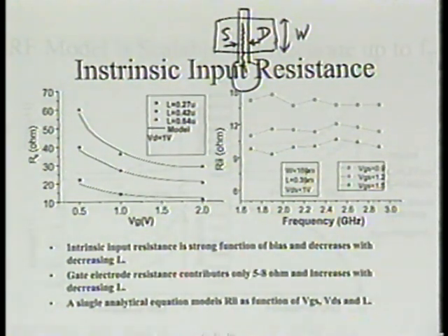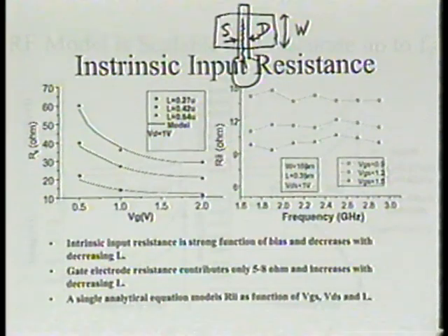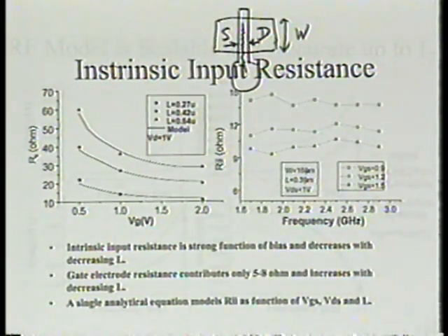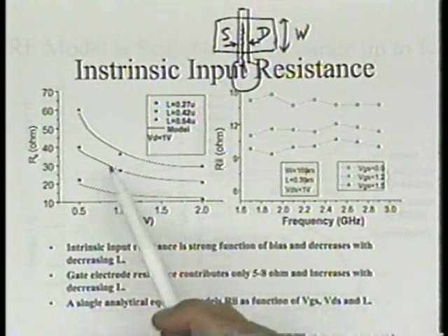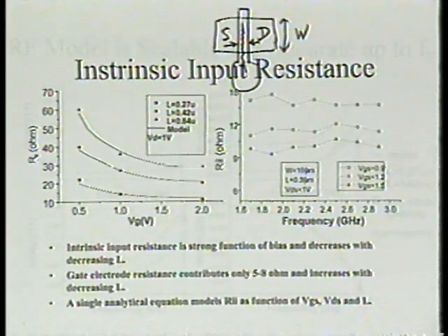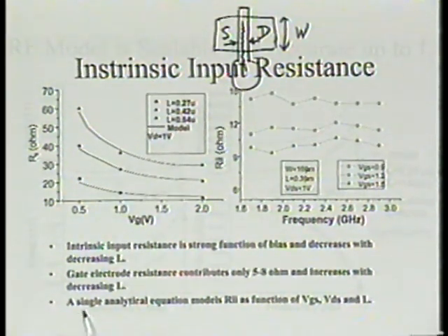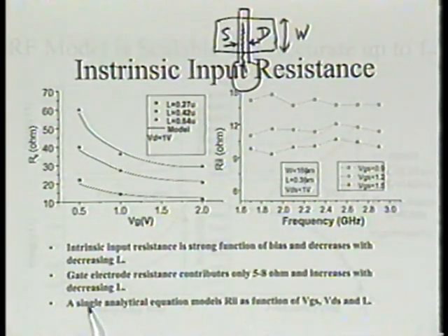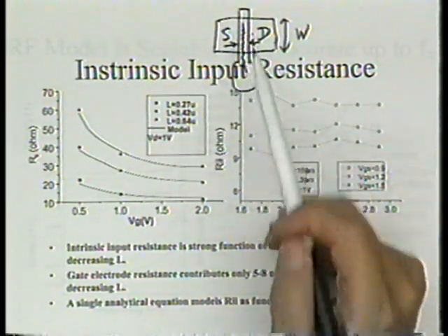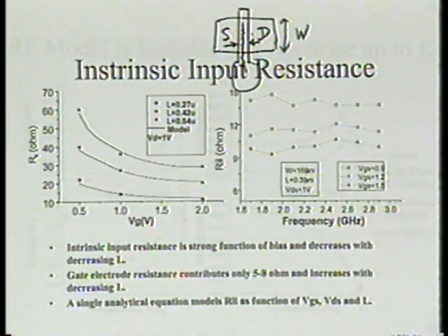Okay? So this is where a lot of people went wrong when they were trying to model this. If you truly treat this as a curve fitting model, of course, it doesn't matter. Just pick one particular resistor to happen to fit that particular S parameter data that you have with particular channel length, particular VG, particular VD, it's fine. But that's actually the wrong physics. Physics is telling us the resistance we see in the input is the channel resistance. What the gate really sees is the channel resistance divided by eta. Now the channel resistance does become smaller or larger when L gets shorter?